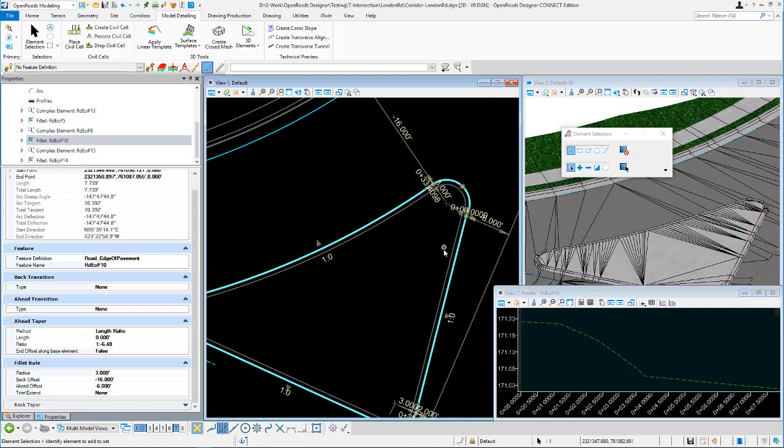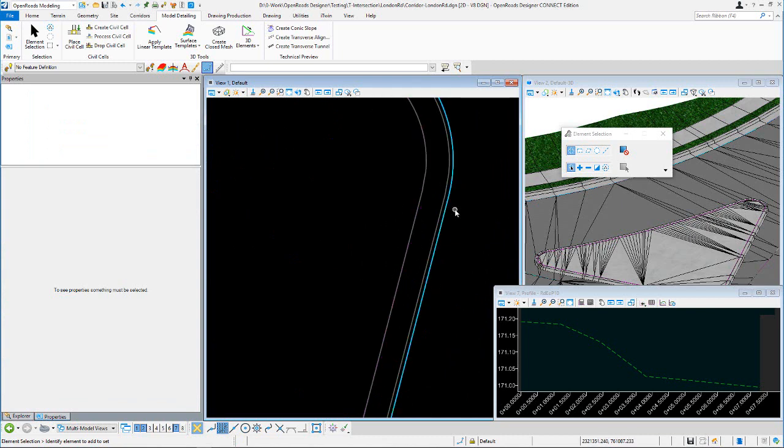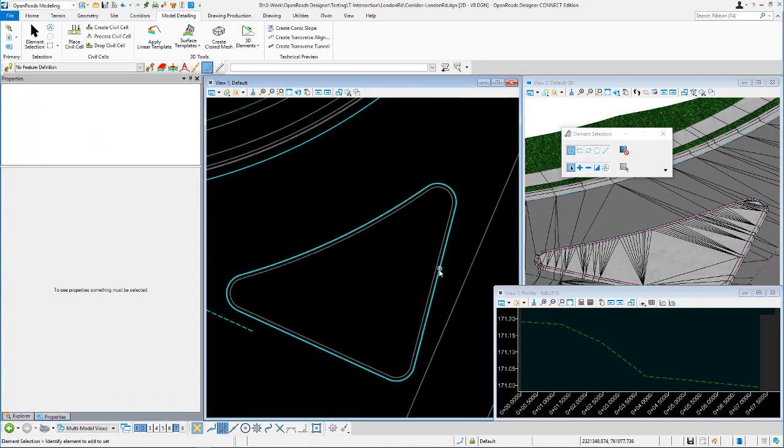So it went the opposite way, right? So what I would need to do to correct that is just come back and take that negative sign off now, right? I can tell that because I see more of a kink there. So I'm going to come back and go 1 to 6.48. And now if we come in and look, there is no kink there anymore. So I've basically added that ratio to this curve here.